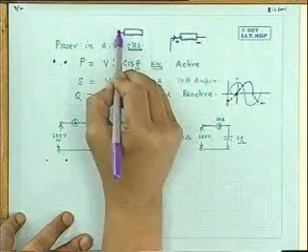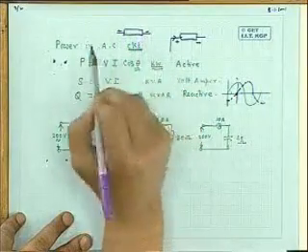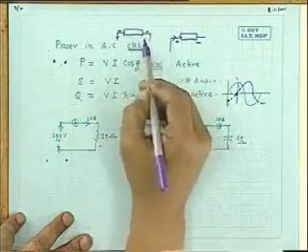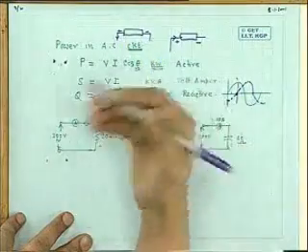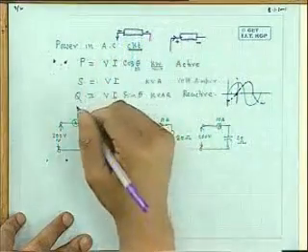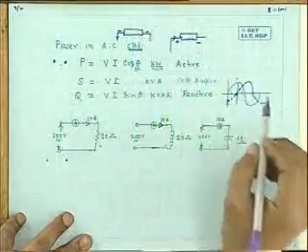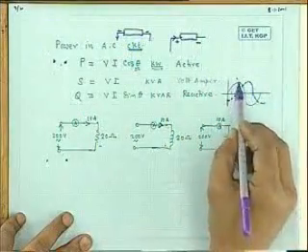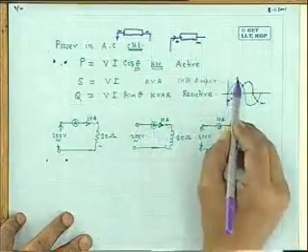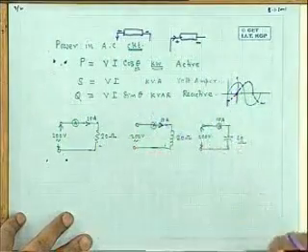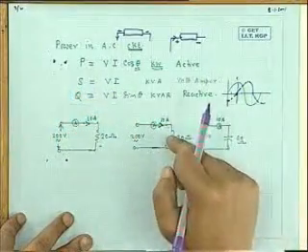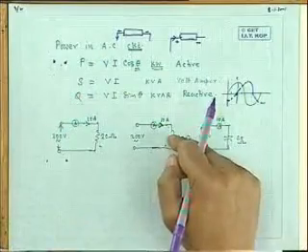Any device which has this side plus, this side minus voltage, and current comes out from the positive terminal, it delivers power outside. This we know from the battery concept. In case of an inductive circuit, therefore, sometimes power will be drawn, you can identify those zones, and sometimes power will be given back to the supply.